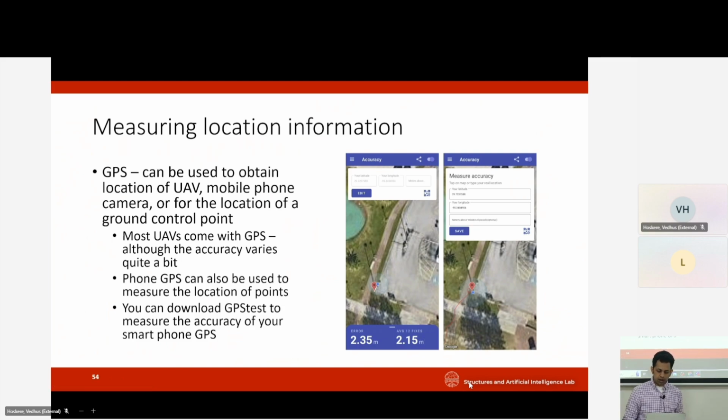So it's similar with the UAV GPS, the regular GPS that you would get, and depending on how accurate you want your scale, that may be sufficient or it may be insufficient. If you're trying to do sort of terrain mapping, or you're trying to do a large area, 2 meters is probably fine. But if you're trying to measure small cracks, and you want the crack width accurately, then that 2 meters may be a problem because your crack width may be off a little bit.